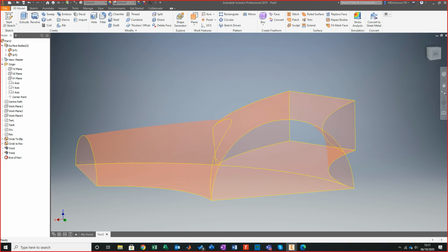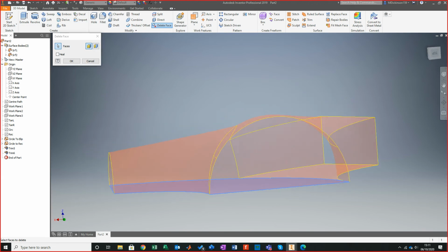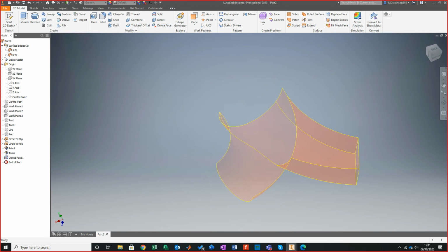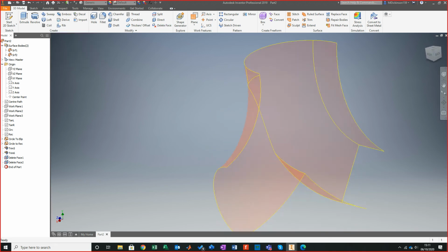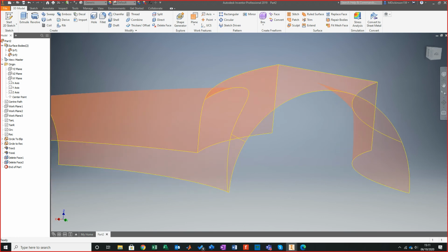It's not always going to be nice for you, and I wasn't trying to be difficult, but it's just a nice thing with it. So all I'm going to do is just delete them faces right out. So let's go on there and delete that, and click OK, and then I'm just going to delete another face of that one. Bring that face in. Get rid of that. And what is a good way to see if you've got any illegal surfaces?